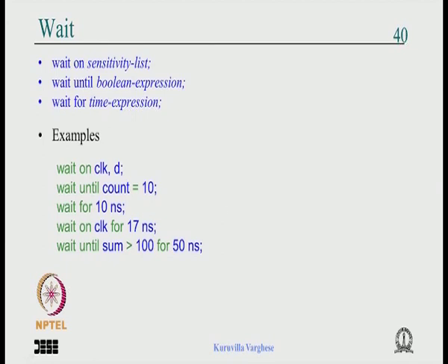Absolutely no problem with the simulation, and for synthesis you have to think. If in the code you can easily work out the structure for synthesis yourself, then it works, otherwise be very careful. And wait for 10 nanosecond is only for simulation. Don't think that you assign some output and say wait for 10 nanosecond, and the synthesis tool will give you a delay of 10 nanosecond.